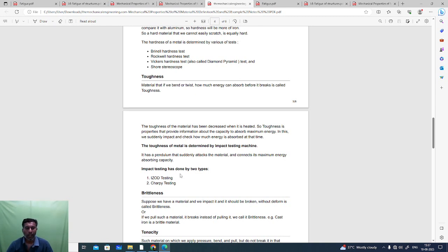Brittleness. Suppose we have a material and we impact it, and it breaks without deforming. That is called brittleness. Or if we pull such a material, it breaks instead of stretching, we call it brittleness. For example, cast iron is a brittle material. When a load is applied suddenly, it will break suddenly.